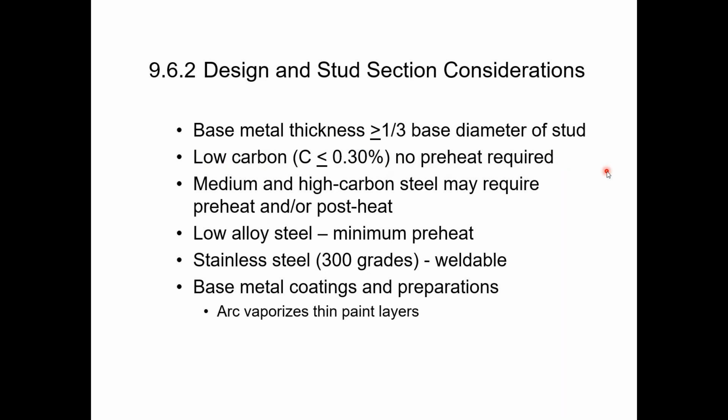It's possible that if you're getting high carbon steel, you may need to do some preheat. So definitely know what you're ordering. Are you getting standard studs, or are you getting high carbon or medium carbon steel? In those instances, you would have to preheat. For low alloy steel, there is a minimum preheat.